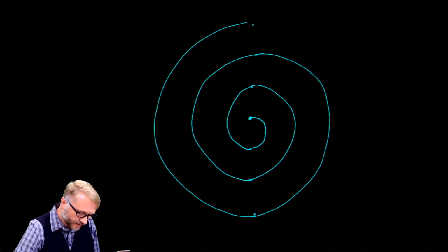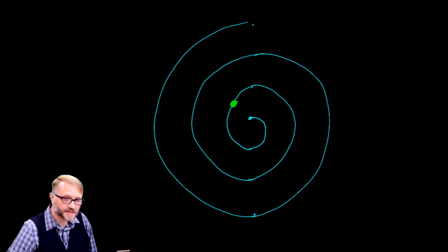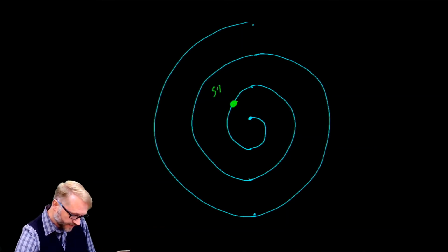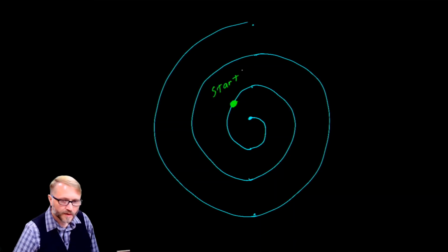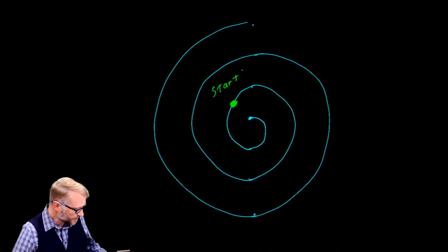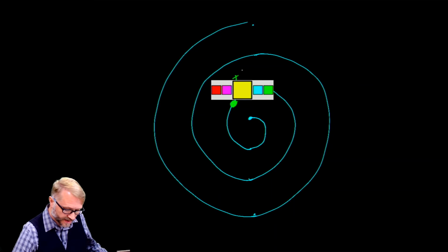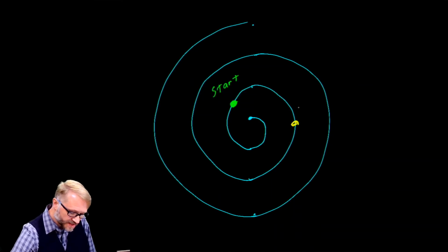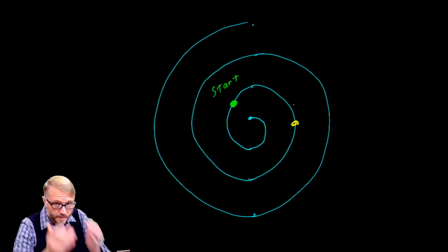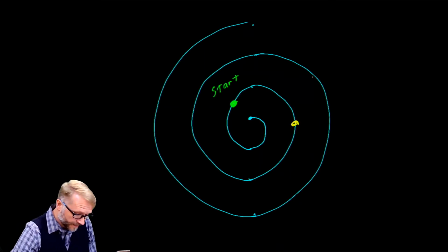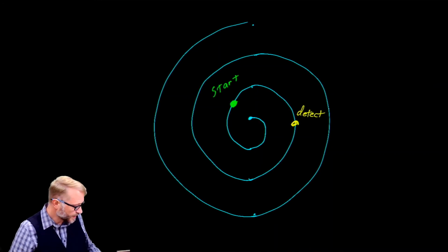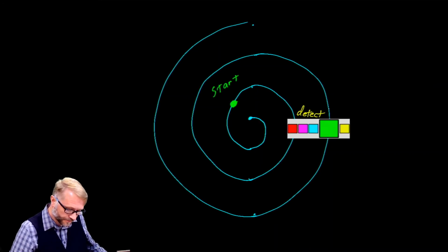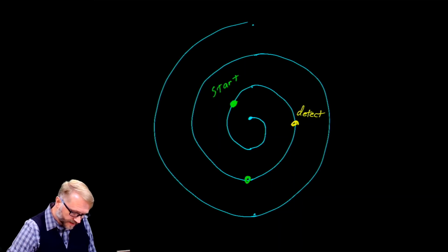For sake of argument, let's assume that the operator pushes the start button right here. So here we have a start button. We know that that will not be detected until the PLC does its input scan. So right here, we detect that the button has been pushed. Peekaboo, right? So we detect here. Your code will handle it here. So we're going to put a 1 here.